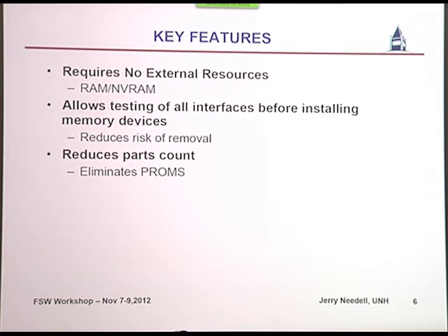The design criteria for this boot code is that it not make any assumptions about external resources. So it can't use the RAM, it can't use the NVRAM on the board. It has to come up and be operable totally within the FPGA.